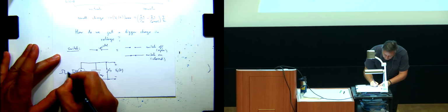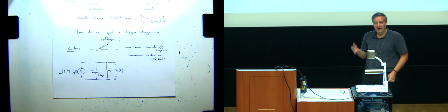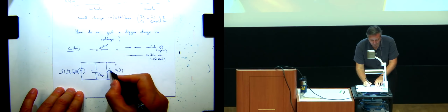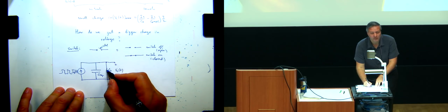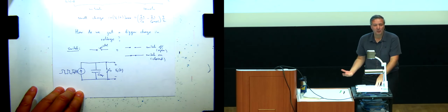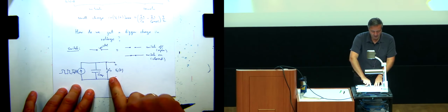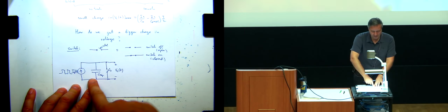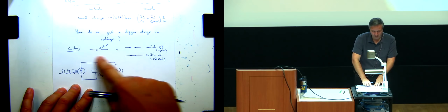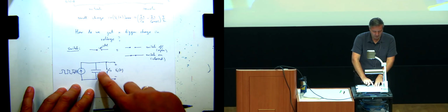Right, this is our periodic source. We can add that element, and at whichever time we want, we would keep the switch on. When we keep the switch on, basically VC of t is equal to 0, right? Because it's just a wire across. So all of this current is going, instead of into the capacitor, it's going around through this wire. And VC of t is 0.